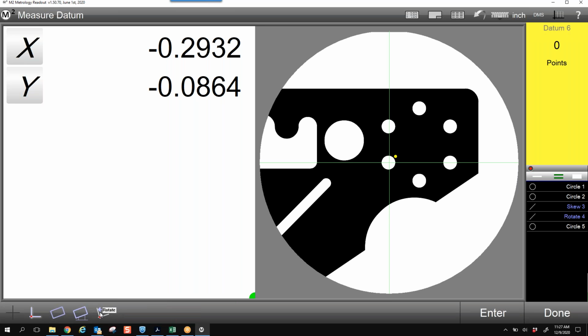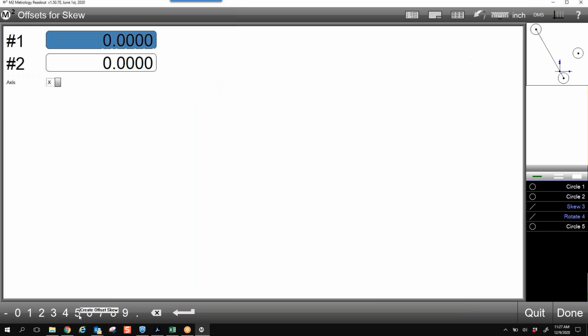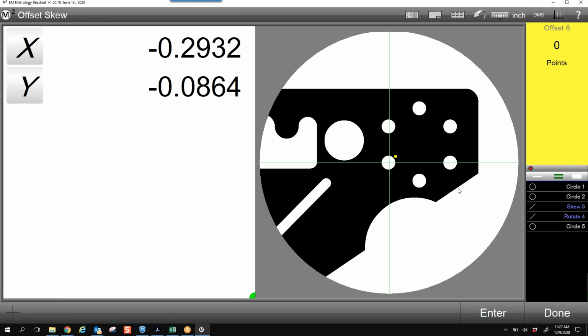So that was the offset right there. So I can put an X and a Y offset, and then it will rotate to that. Okay. So if it's a circle and I didn't know what it was, I can offset to a given number, and it'll do it either by X or by Y by switching that. Okay, great. So you're not offsetting the 0 point of your program, you're actually offsetting the skew then. That's what I wanted. Cool. Thank you. Yes.